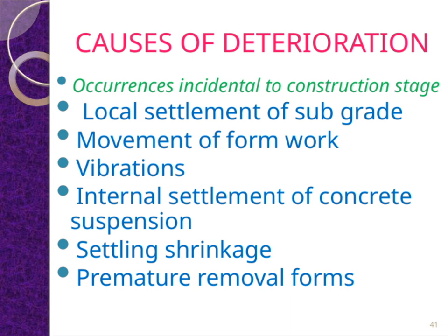Next, there's the movement of formwork, which occurs when the temporary molds shift or settle before the concrete cures fully. This movement can cause surface imperfections or misaligned elements. Then we have vibrations, which can be caused by nearby construction activities or equipment. Excessive vibrations can lead to internal stress within the structure. Internal settlement of concrete suspension, another point, refers to the slight sinking or shifting of the mixed concrete before it fully hardens, potentially leading to uneven surfaces.